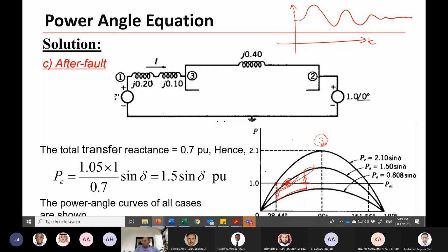If I understand your question, you are asking whether there is any scenario where the post-fault curve is higher than the pre-fault one. Actually, no, unless you have another switching of a series capacitor or static var compensator, or you insert another device in the system.